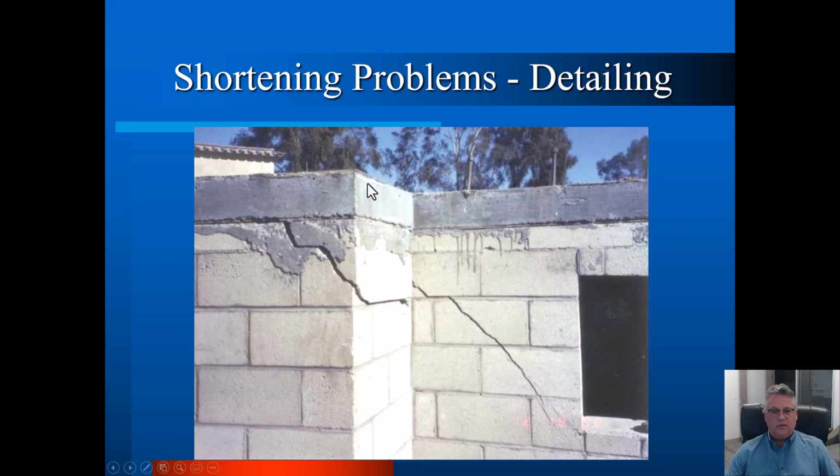If you look closely, you can see that there is a steel plate here. It's waiting for a corner column that's going to come, a steel column. We met with the engineer and said, our slab is going to move. In fact, we have masonite board in between the slab and the wall.